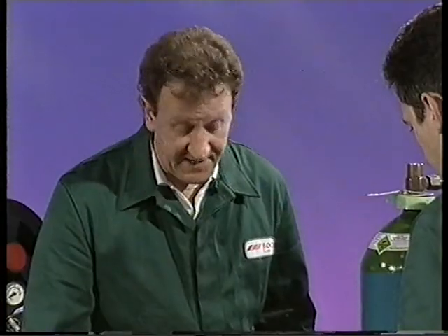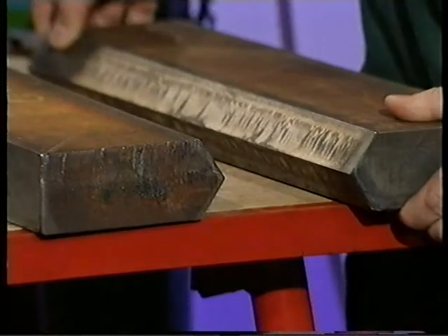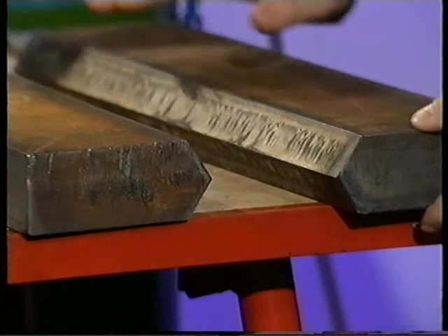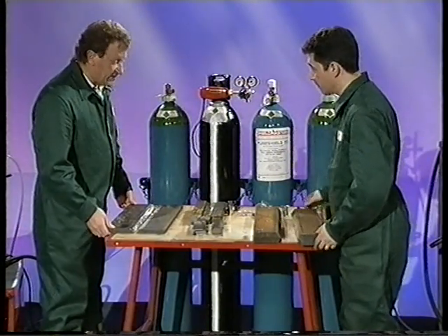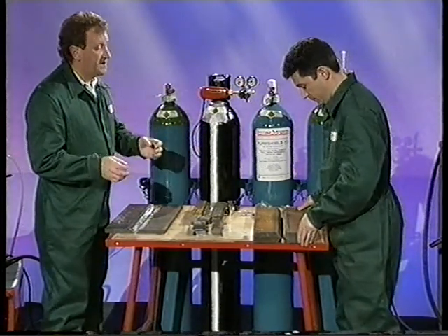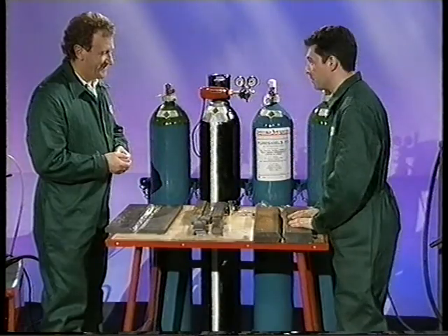For even thicker section work, such as the one near you, and if you're able to get to the reverse side, we use a double V. Right, that's a really thick section. And so what you're aiming for is filling that gap with weld, aren't you? Completely filled up, so it's completely fused throughout the thickness. Okay, I can barely move that, but let's try and weld it now and set the equipment up.